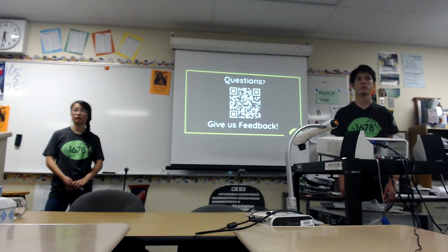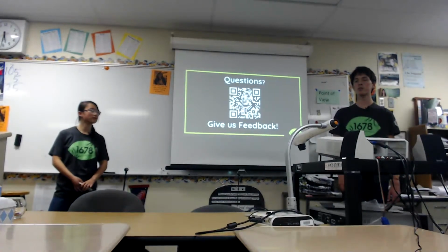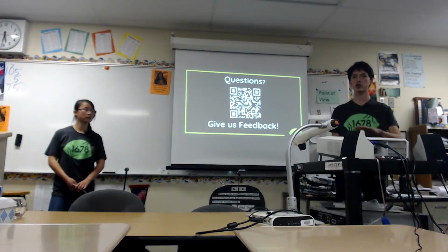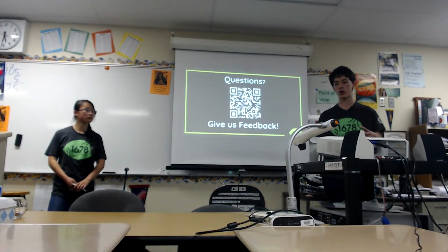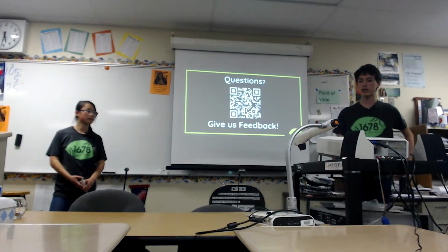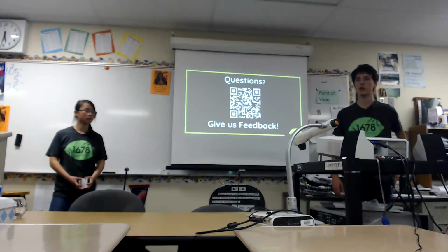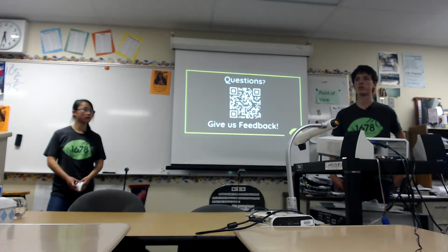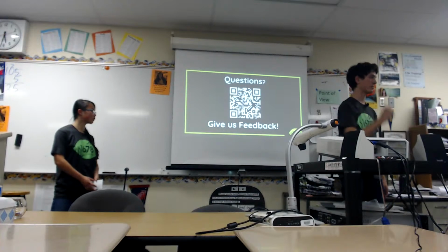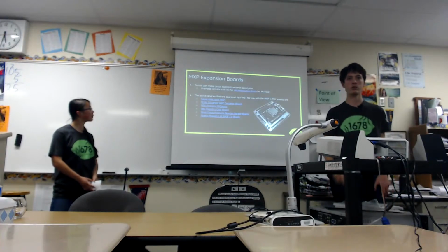You mentioned the Spartan. What's a Spartan board? A Spartan board is something made by West Coast Products, and it doesn't just cover the expansion port. It covers all of the ports on the RoboRIO, so it's a way of taking the expansion port and integrating more digital input-output ports and more PWM pins in, and it's also a gyro sensor. I think we have a link to that on the expansion board slide.